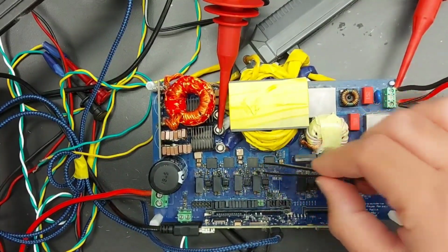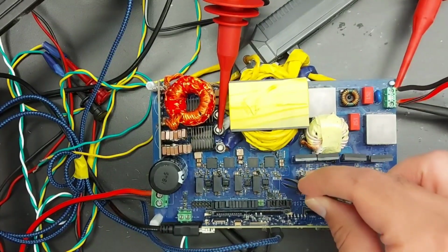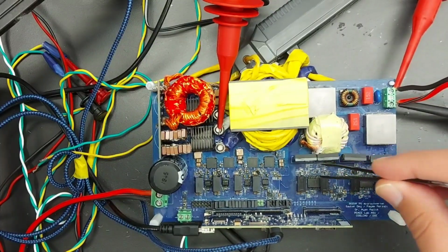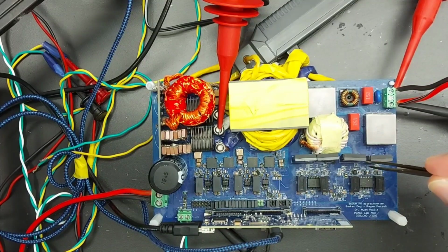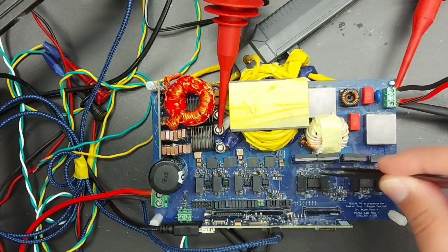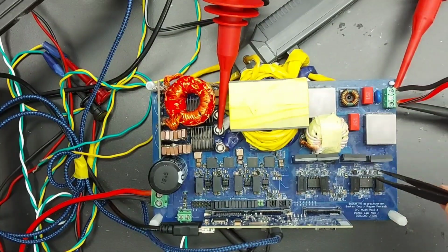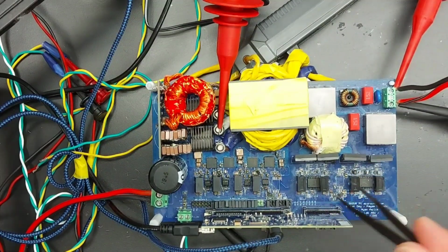After this secondary bridge, we have the rectified sine wave voltage waveform here, in between the secondary bridge of a DAB and the unfolder switch. The duty of this unfolder switch is to unfold this rectified sine wave into a pure sine wave, which is then connected through an EMI filter to the grid. Since we are switching at 60 Hz for this unfolder switch, we can realize the switches with 6 MOSFETs, which is less expensive.